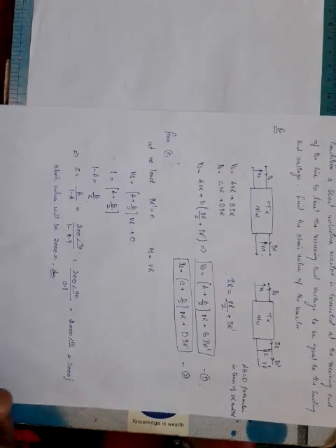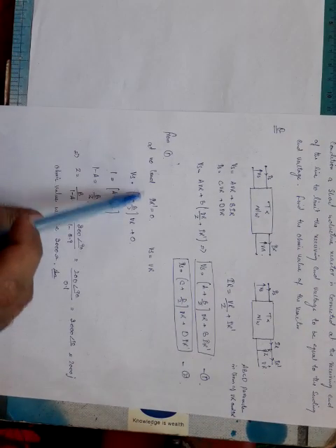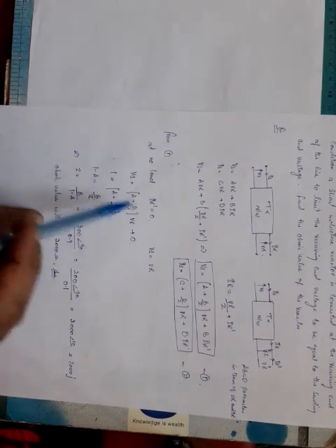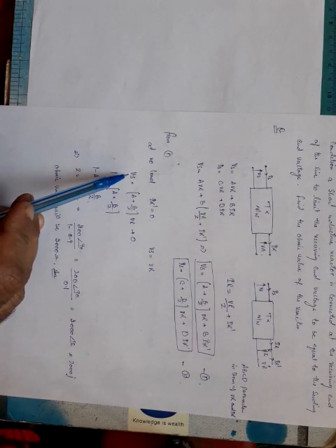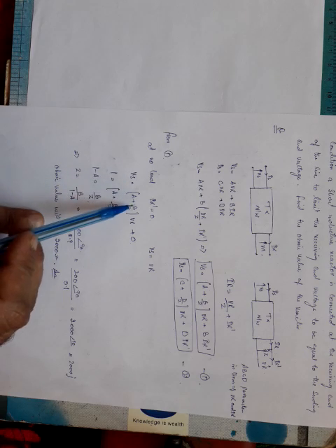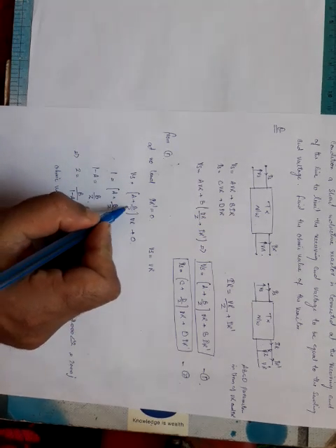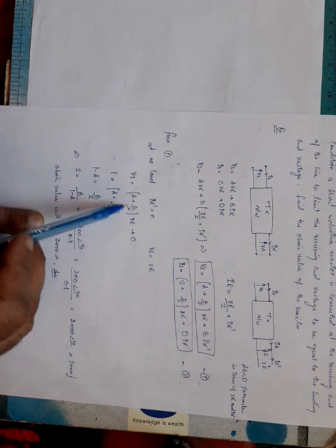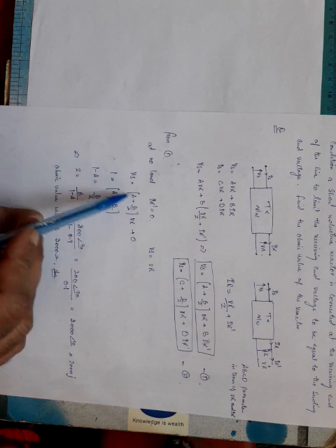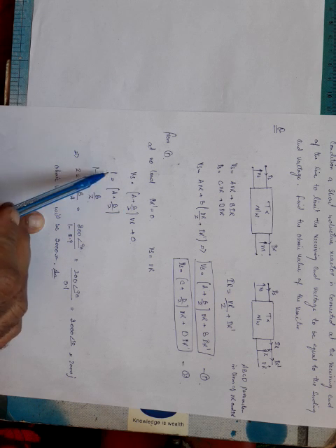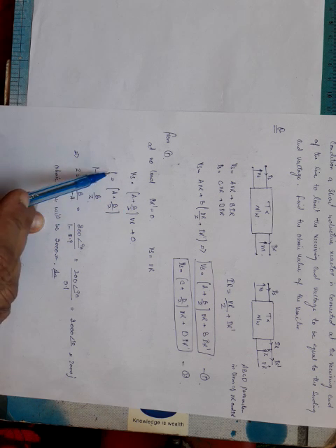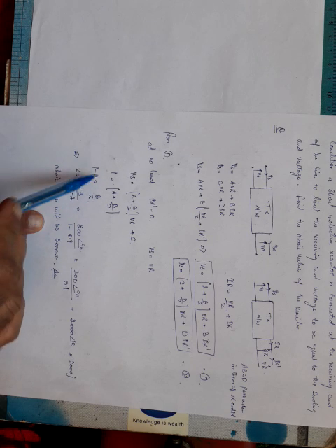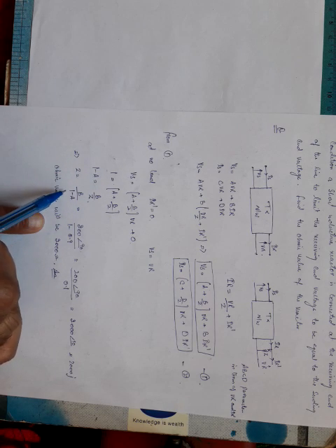Now from the first, you can see at no load IR dash is equal to 0, like we did from here. For this case, this equation reduces to Vs is equal to A plus B by Z into VR plus 0. That means when Vs is equal to VR, this term should be equal to 1. So I have taken A to this side, it will be 1 minus A is equal to B by Z, or Z is equal to B divided by 1 minus A.